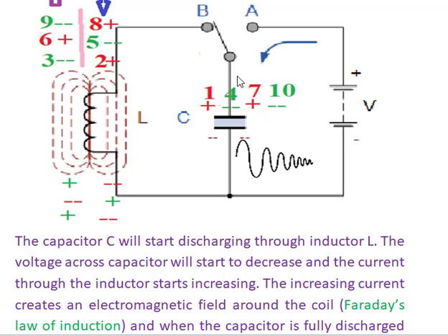See here, this negative voltage again coming here, so here now negative, automatically here positive. Now, this negative voltage and this positive voltage again produce the magnetic field. This magnetic field starts to fall or shrink after the capacitor is fully discharged.